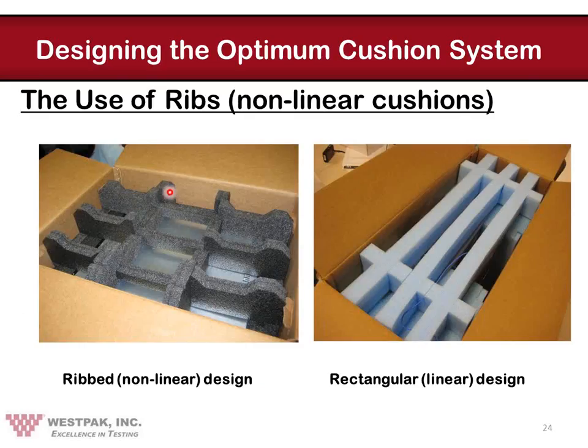These are more or less trapezoidal shaped ribs, and you can see they're very consistent with the design of the product and the package system. They work very well. And again, the vibration characteristics are determined by the peaks of the ribs. These are the points up there, because the deflection necessary for vibration is very, very small because the acceleration levels are very small. Okay. For impact, not the case. You've got all this material available for your impact characteristics.